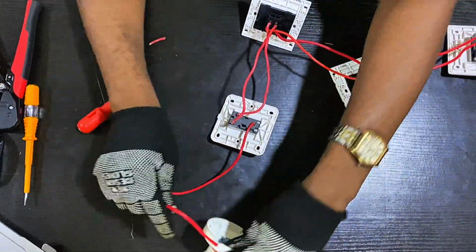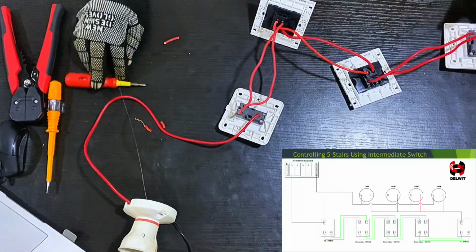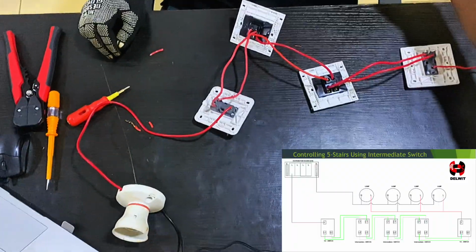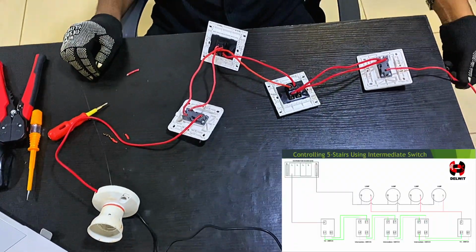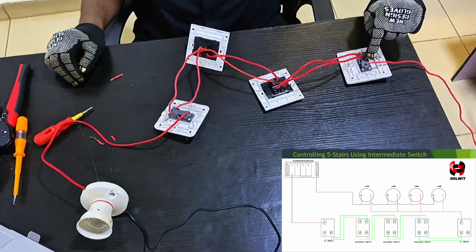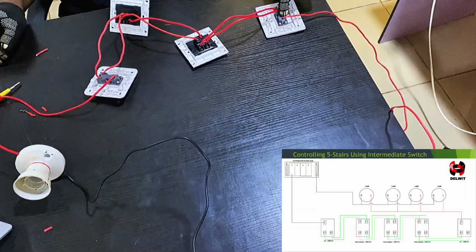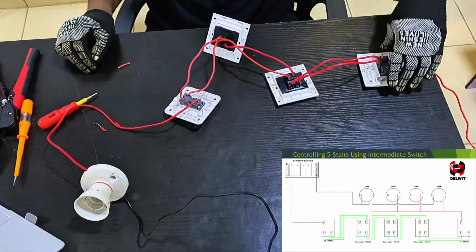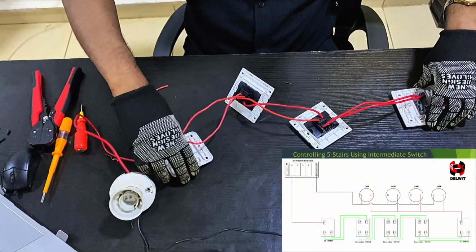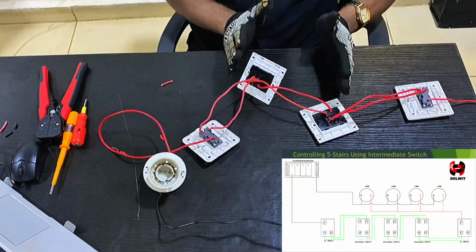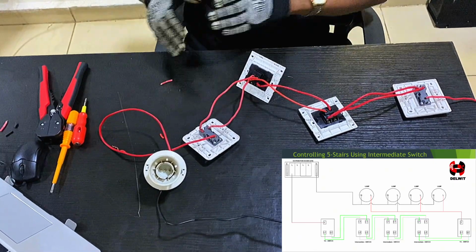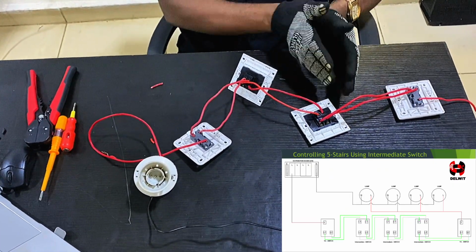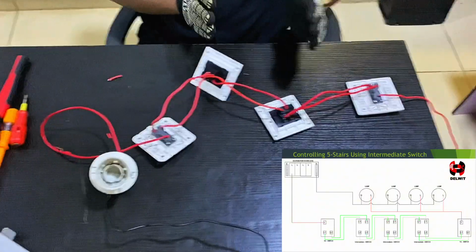So you can now see from your circuit diagram that the live from the circuit breaker on your DB is connected to the common of the first one gang two-way switch. You can see that on the ground floor you have one gang two-way switch. On the last floor you have one gang two-way switch. Then in between the floors you are going to have intermediate switches. So even if it's 20, 30, 40 floors, in between the first and the last is intermediate switch.